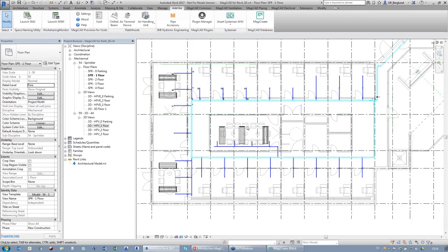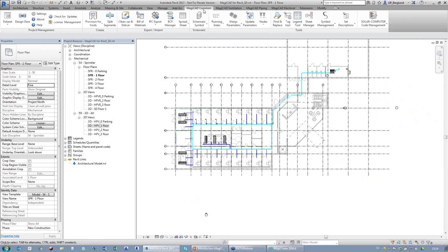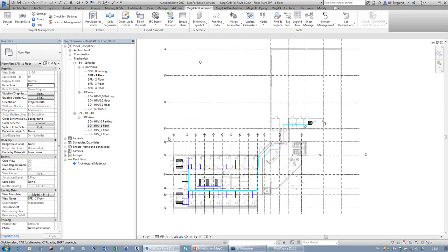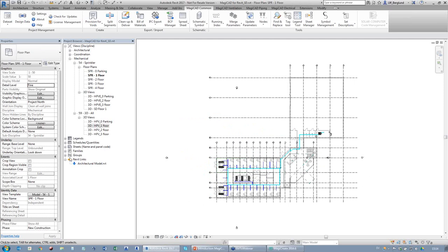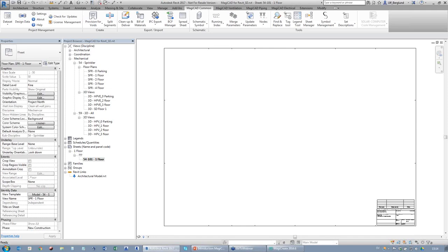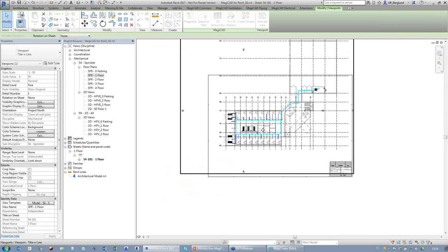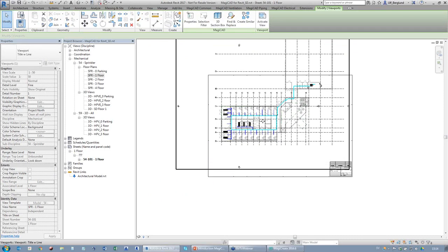So that's those parts. Then I can make one more thing, maybe show the sheet manager tool. Let's say that in my case I have this floor 1, and when I'm on this floor, I want to make some sheets to be able to plot this. This house is too big to be placed on one sheet. If we go in here and I drag my floor 1 into this, you can see that there is no way I'm going to be able to fit my whole house.